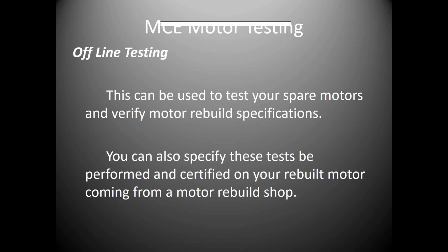In testing 240 spare motors at a facility, we found about 40% of the motors wouldn't have lasted a year if they had been put online. Many of these motors had been through the motor rebuild shop, but with poor rebuild standards. The company I work for used this equipment to test their motor rebuild shops. They were using 106 motor rebuild shops across the U.S., and only 6 of the shops passed the audit because they weren't doing some of these procedures. So sometimes we demand that the motor rebuild shop buy this equipment.